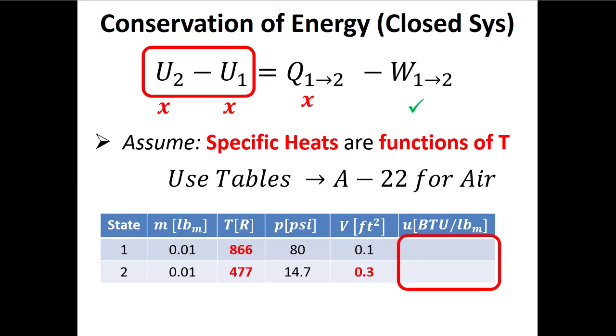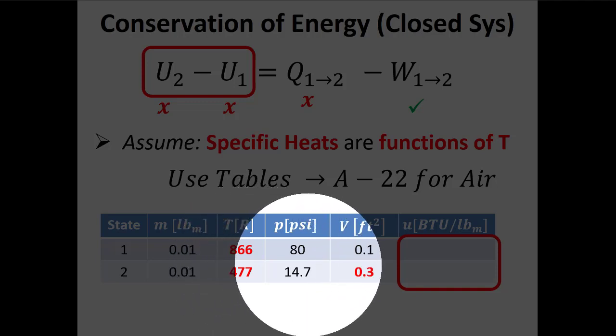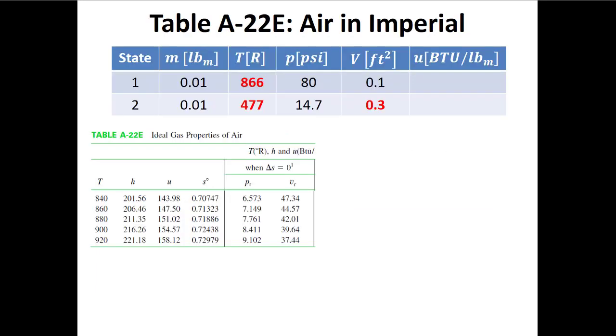So now I've got to make myself a state table, which I probably should have done in the first part too. The ideal gas law stuff that I did to find the temperatures, I can do that too. None of that depended on having a constant specific heat. So everything else here, finding the volume and the temperatures, all works. It's just that now, when we're using variable specific heat, we have a different way of finding the specific internal energy.